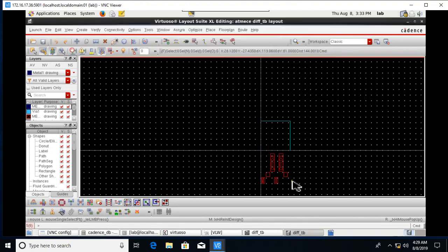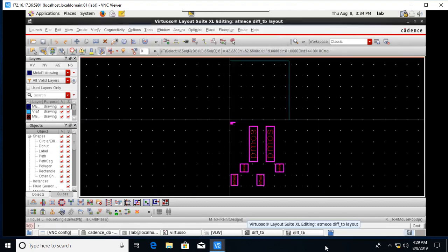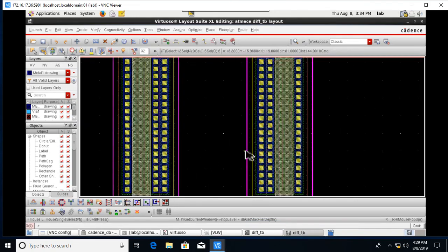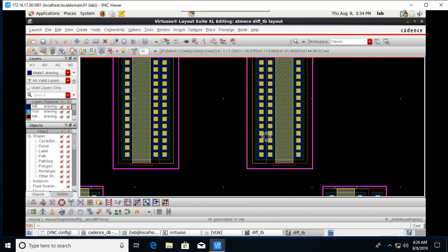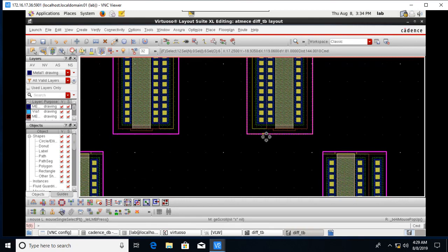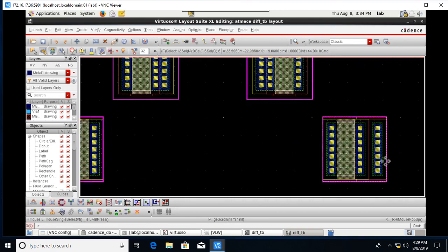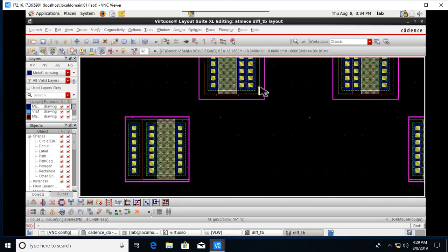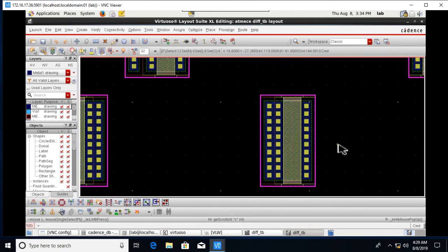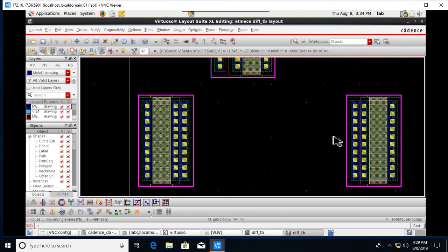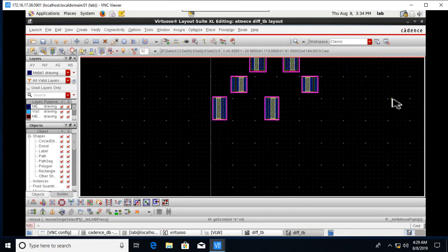You'll get the components. First select all the components, change the view first and check whether the properties have been implemented or not. Here we have given as integrated. The components are integrated, that is the terminals, not components. The terminals are integrated, the source and the body terminal, and it is detached. You can clearly see here the difference between integrated and detached terminals. And here also have given the integrated, so the properties have been changed according to our parameters.